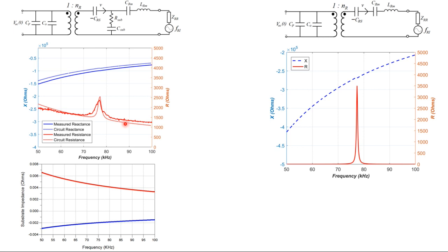If you have a 2D symmetric model with the thin backing, you assume that thin backing is an isotropic, homogeneous medium of, let's say, glass or silicon, and you have to introduce isotropic loss factors. It can be anisotropic, but that would be difficult. You need some knowledge of the matrix, which is difficult to predict.